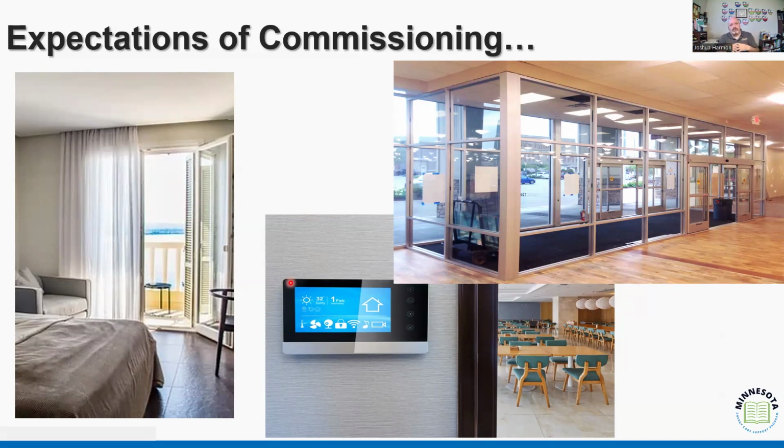If we're doing a multifamily, if we're doing a hotel, right, we want to make sure that those systems are designed to where when the balcony door is left open, it deactivates that. We're not trying to heat, because what will happen is you'll have some crazy guy who brings his kids and they leave that door open on the balcony and then they go out to eat. And we don't want all of that mechanical, all that energy going into heating the space in Duluth while the air escapes out the open patio door. So we need that kind of interconnected door, a hard connection to make sure that, again, when the door's open for an extended period of time, that it shuts off the system.